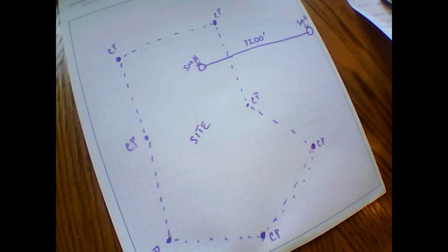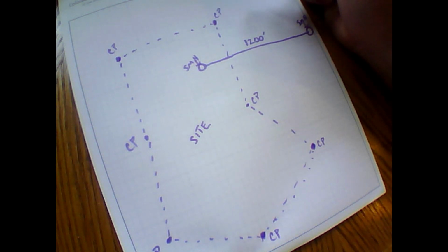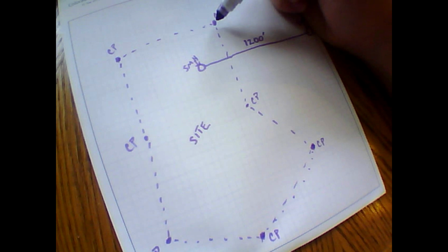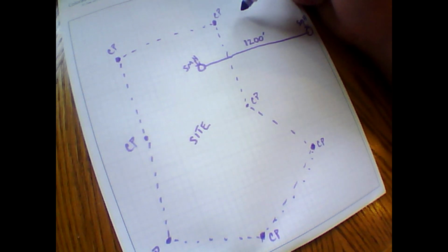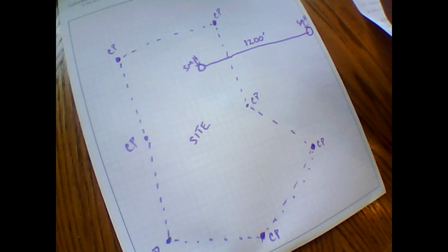You're mixing and matching things that you shouldn't be, in my opinion. You should be on a no projection, no datum. It should simply be, I don't know where I am on the Earth. This northing and easting equals the latitude and longitude I got. When you're in no projection, no datum, all you're going to get is latitude and longitudes. You're not going to have any northings and eastings.